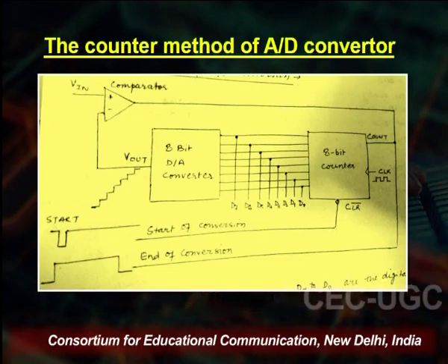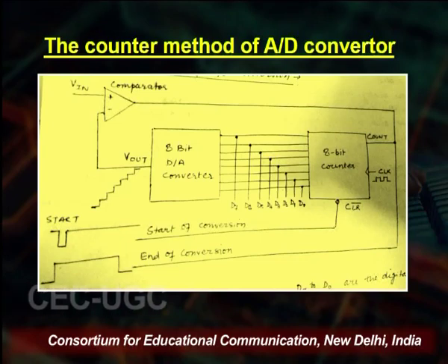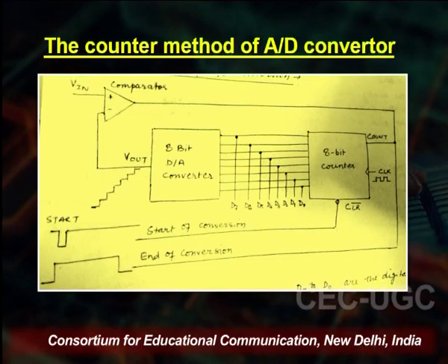So, more cycles were conducted and we found from 2 to 3, 3 to 4, and then it became 5. The moment the output of the 8-bit DAC became 5 volts and was fed into the op-amp, effectively the input voltage that was initially taken to be 5 volts, we have 5 minus 5 is zero, the voltages are equal at both the points, and hence the output of the op-amp now changed from positive saturation to negative saturation.